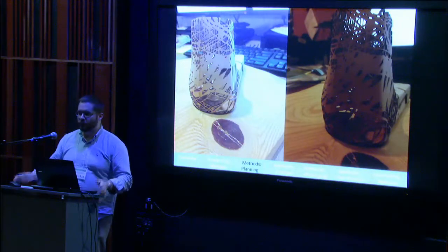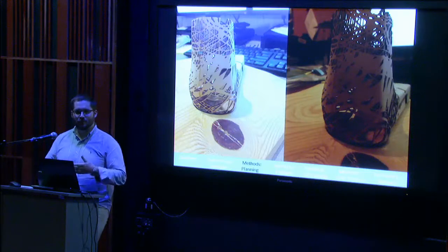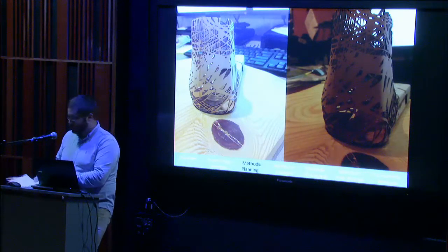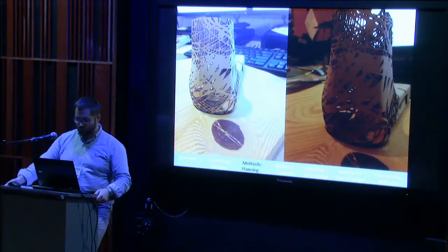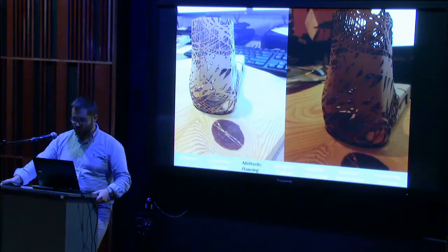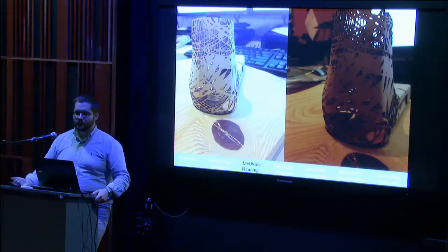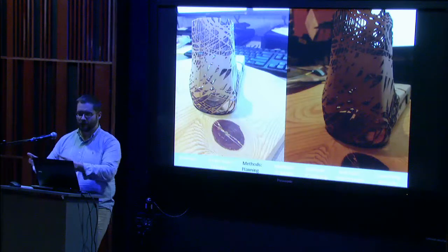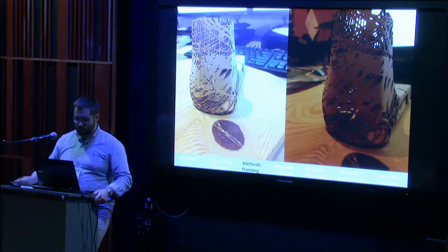And I'm sure a lot of you are already very familiar with the photogrammetry process, so I'll try to keep it brief. But for those of you still learning, we taught them a lot of the basics of how to do a photogrammetry campaign, and the golden rule that we've discovered along the way was that you need to always minimize the number of inconsistencies that you have, whether that's your camera settings, whether that's controlling the subject itself. Whatever you do, try to minimize any sort of change that happens from when you take your first photograph to when you take your last one.